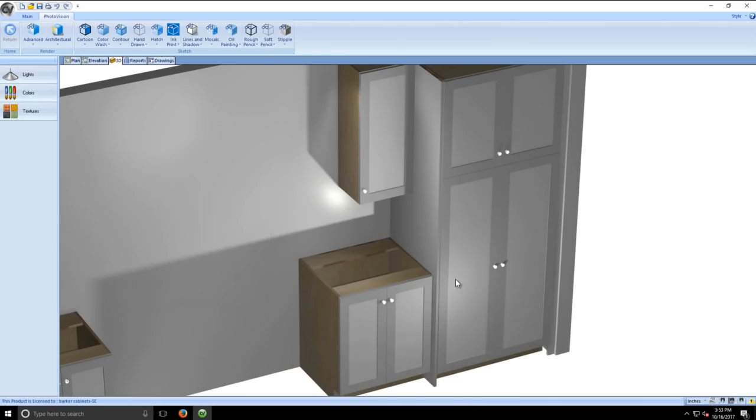Wall cabinets are 12 inches. Base cabinets are going to be 24, tall cabinets are 26. So that's the depths. Again, heights can be whatever, widths can be whatever you want. It doesn't matter. And they go right into it. There's no filler between this wall cabinet and the tall cabinet there. So there you go. Pretty cool. Pretty nice look there. We got the right elevation for the wall cabinets.